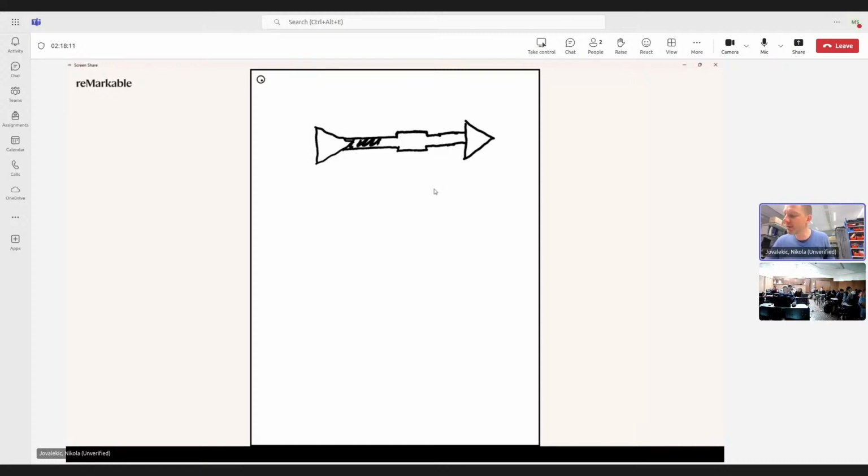So this is the trace, all this. And the signal needs to go from this point to this point. What will happen? Signal will travel to this here, and then you will have one part of the signal bounce back, and this will continue here. This will be bouncing here in between this discontinuity until the energy disappears.